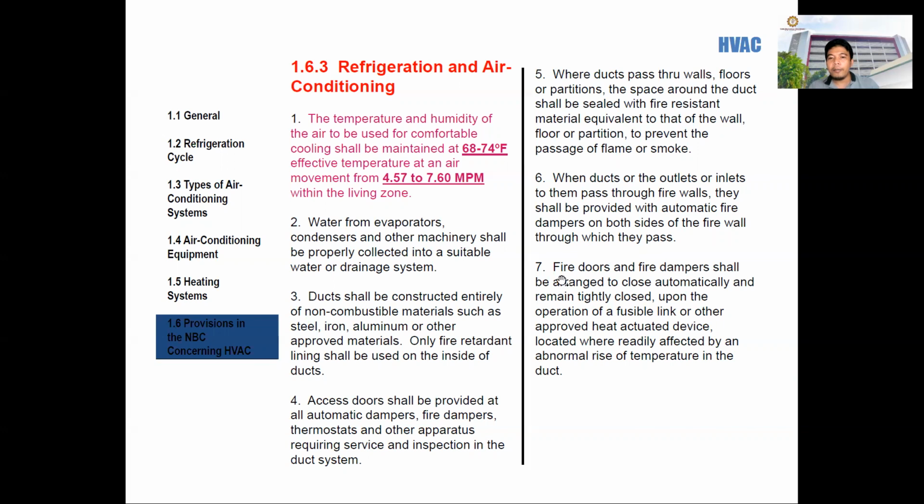And then number 7, fire doors and fire dampers shall be arranged to close automatically and remain tightly closed upon the operation of a fusible link or other approved heat actuated device located where readily affected by an abnormal rise of temperature in the duct.